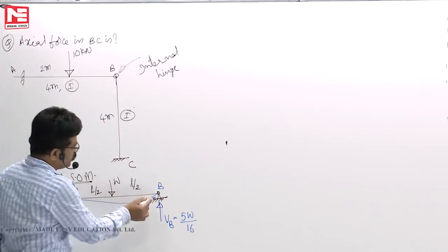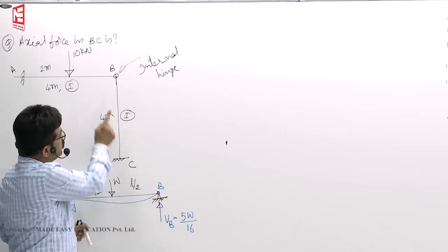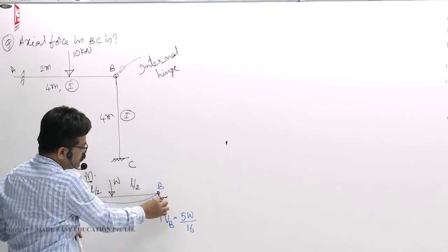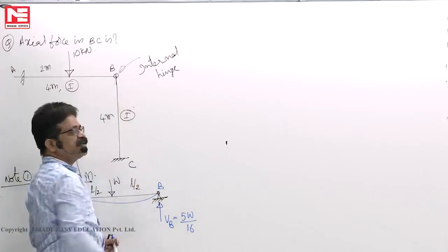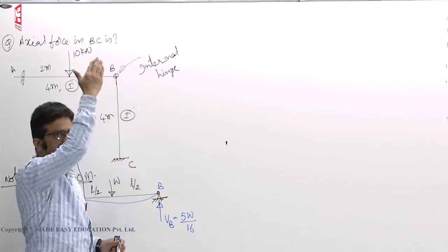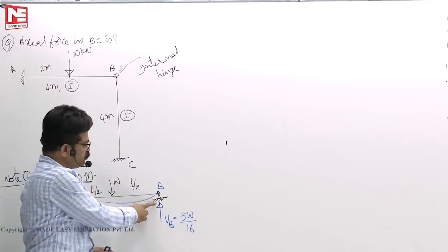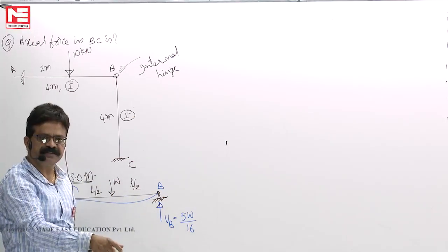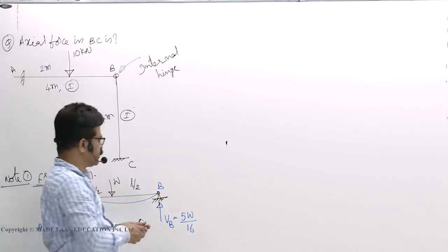Now this problem and this problem, only difference is there is a hinge support here. Here what happened, instead of that support, what we have shown here is it resting on a column. This is a column generally. Instead of showing entire column and wasting the time, simply hinge support you will take it. Support means it should rest on something. That resting place is the column. We can take it that way.